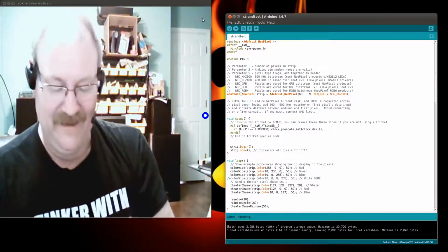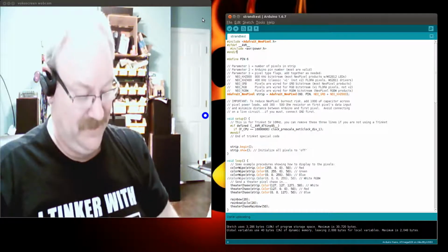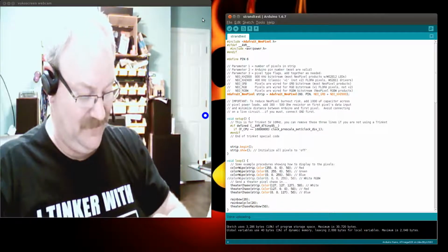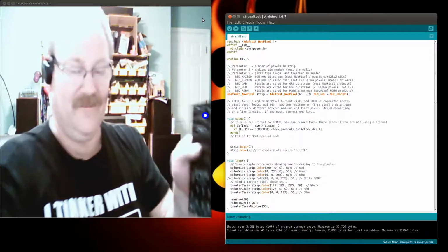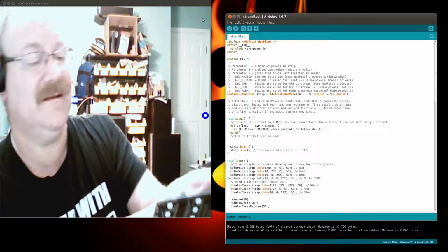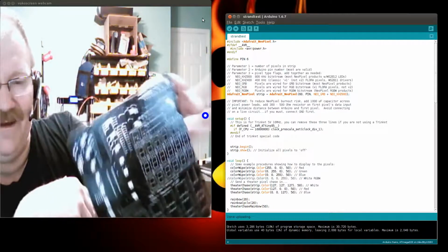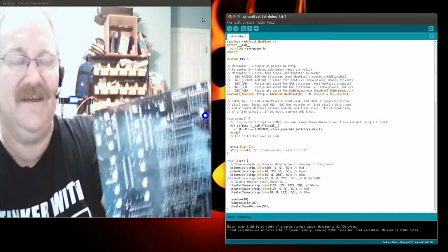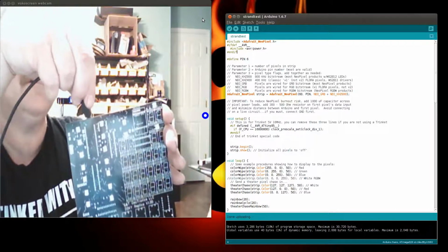So we'll take our Nano off of this board, and we'll grab this other board over here, and we'll put our 470 ohm resistor in the resistor hole. Just like that. We'll take our Nano once again that's already programmed. We'll put it on the back of it. I'll grab it in that special way so I've got a hold of it, just like that. And then we'll apply power to this thing, and hopefully, very hopefully, all of them will work.